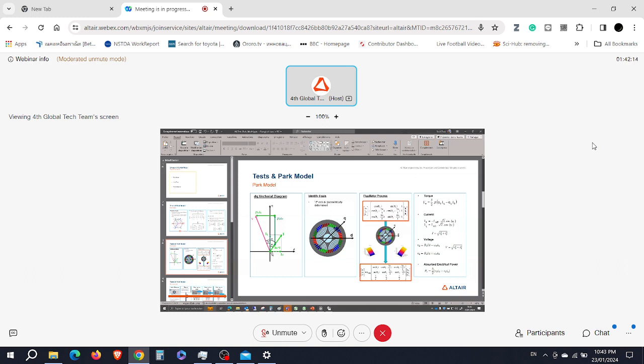So this is equal to the voltage. Then our control angle, in our case, is psi. We can see phi, the phase angle between the voltage and the current, which will give us the power factor. If you remember the vectorial diagram, the control angle for the permanent magnet machine is in this quadrant.